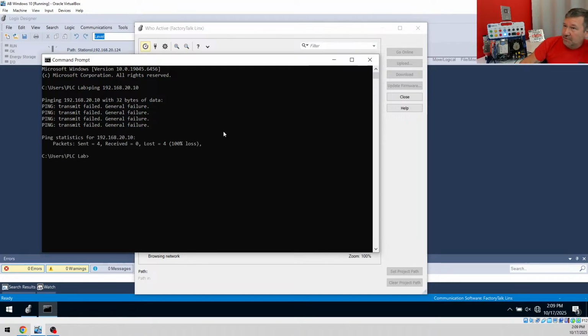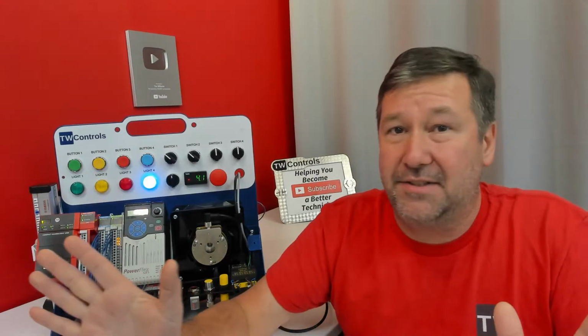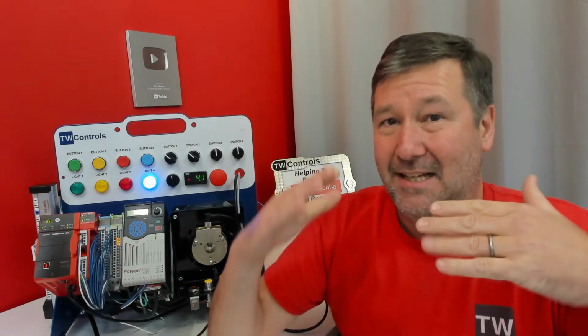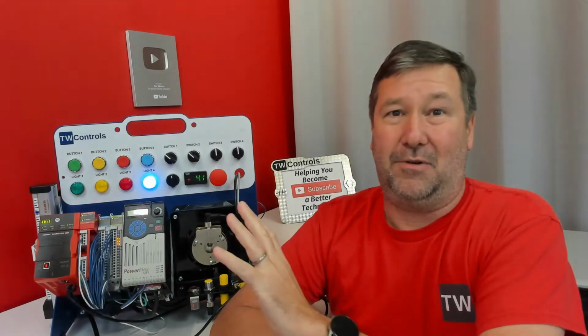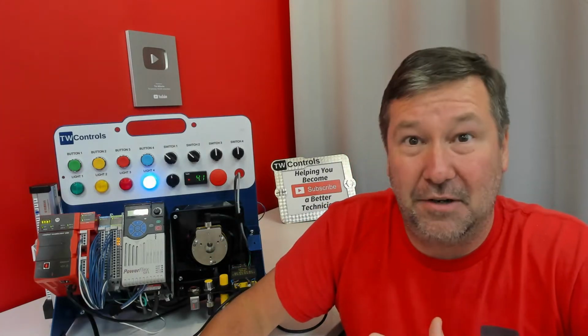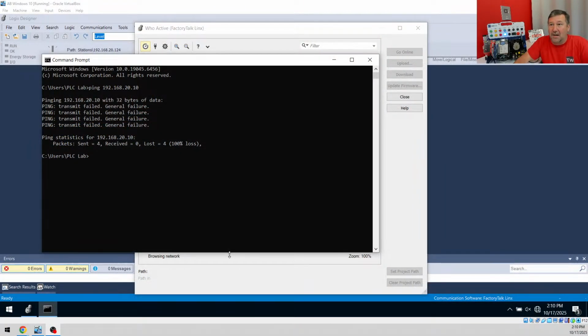And we're getting a bunch of general failures. Now, 100%, if you cannot ping your PLC, do not go into Studio 5000 and start messing with any driver configurations or anything. The ping command is saying that your Windows computer cannot talk over the network to this PLC. We're not even into the software realm of Studio 5000 yet. And so the other command that we need to know in our command prompt is ipconfig.